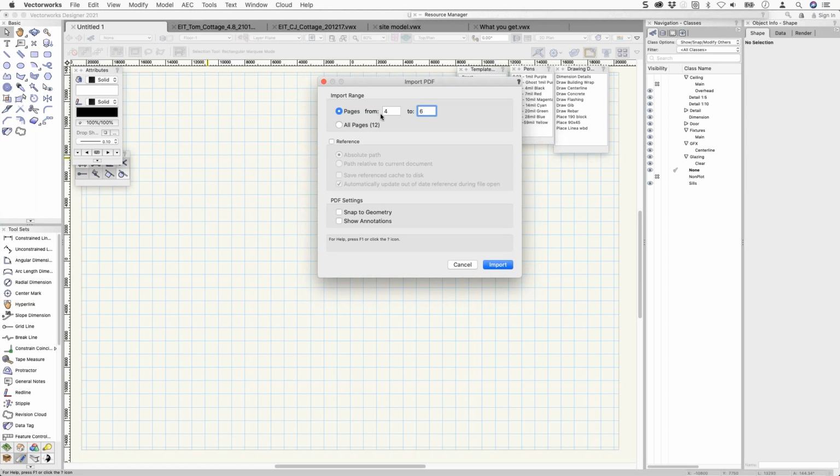Now, if you're going to bring a lot of PDFs from other people in, one of the things we use for annotation, when you've got a lot of detailed construction notes that you want to put into Vectorworks and you want them beautifully formatted and in columns and things like that, why not write those long detailed notes in Word and then export that as a PDF in Word and import that into your Vectorworks so that it fits the page, it's got all the formatting you want, it's got the right emboldenment of the things.